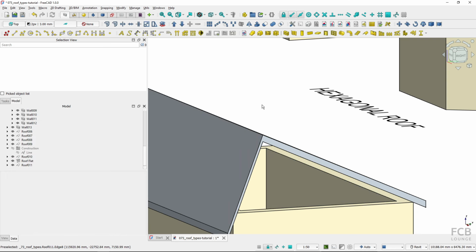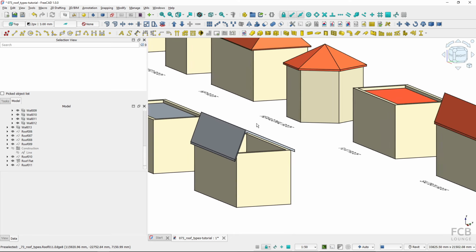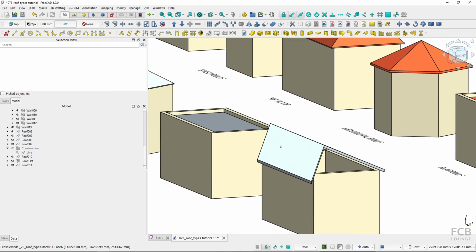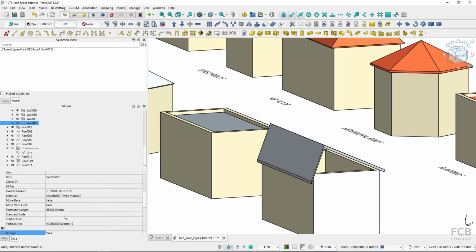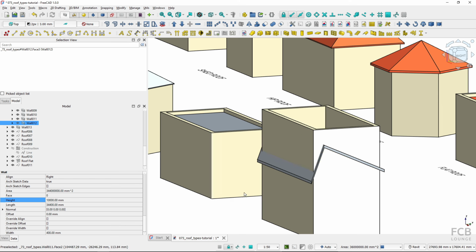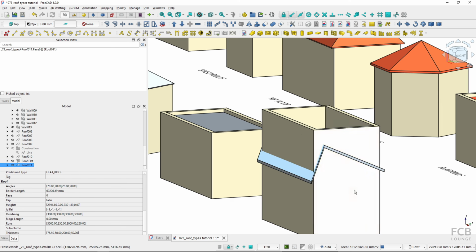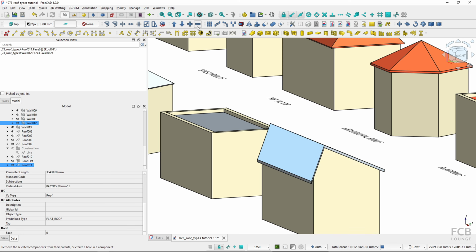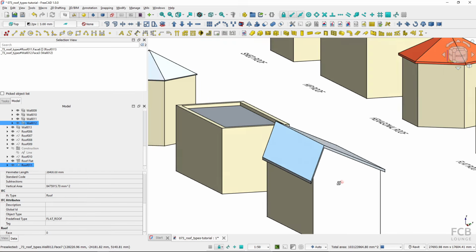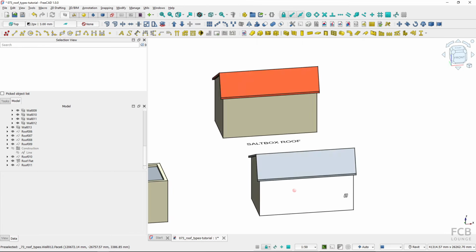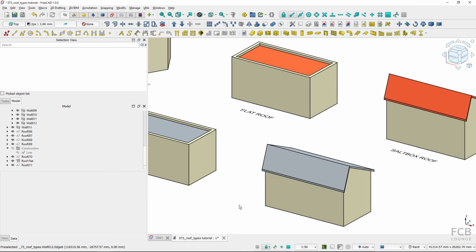So now I will close the roof, and now again we will use the same technique to attach the walls to the roof. So I will select the wall object, change the height to 10,000 millimeters. Again, it's higher. Now I will select the roof with Control, select the wall, and use the Arch Remove object. And you can see that our Saltbox roof is complete.